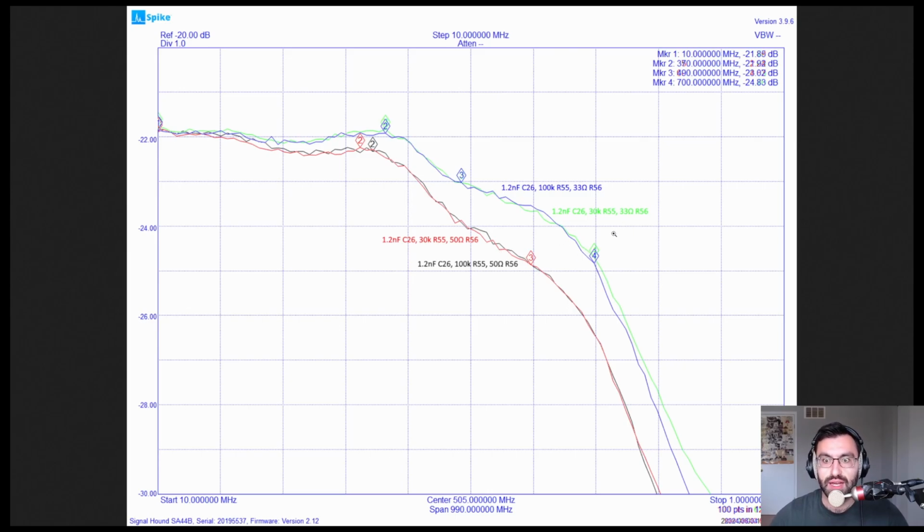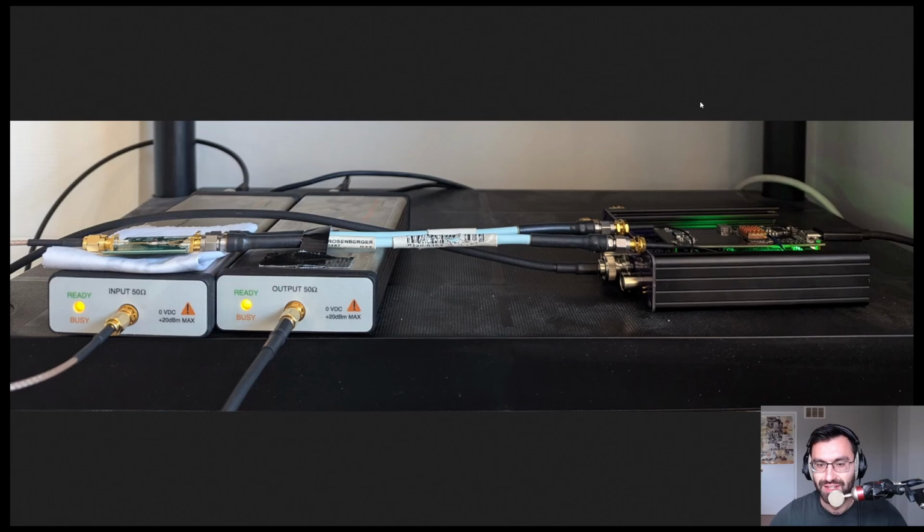And that also lines up nicely with the inbuilt bandwidth limits in the PGA, which, for the higher frequencies, are 600 and 750. So if we turn on the 600 bandwidth limit, then we should essentially be able to normalize a lot of these gains to be the same bandwidth. It won't affect what's going on up there, but at least we can have a more consistent bandwidth across all the ranges. Oh, and that's it for my little slideshow here.